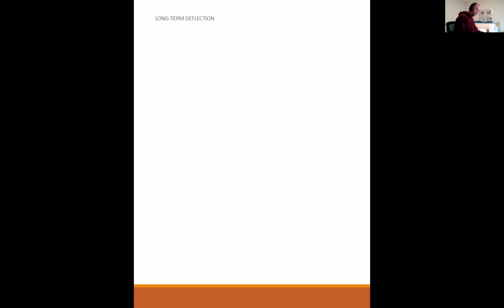So when you get to page 119, you're going to calculate a value of little a, and that little a is either going to be thicker than the flange or it's going to be less than the flange. And that will tell you if it's rectangular or true T-beam.